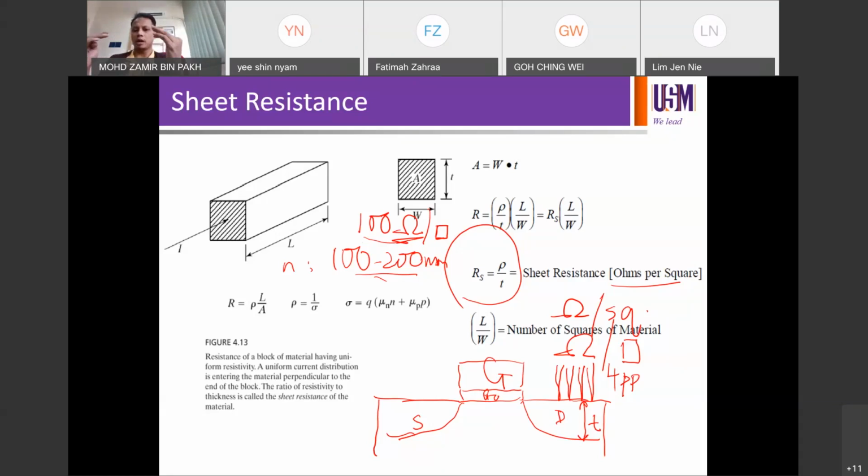But going to a very heavy doping, higher than 10^20, your device or the layer is subjected to Auger recombination. We discussed recombination last time, right? Do you still remember how many recombination types we have? How many recombination types do we have in a semiconductor device? Three.